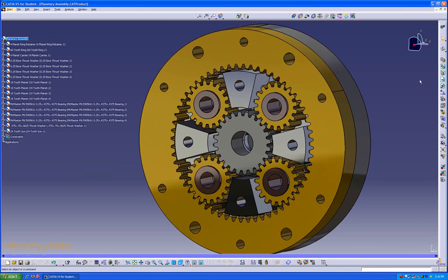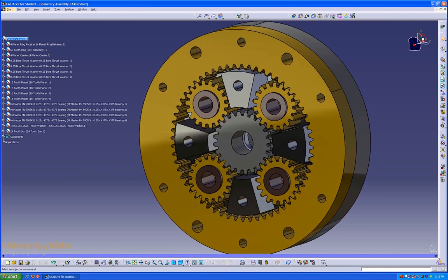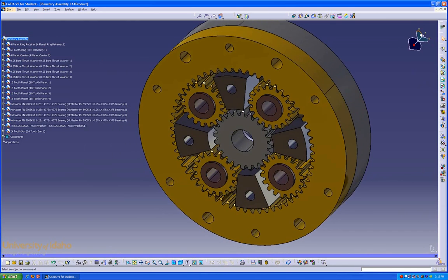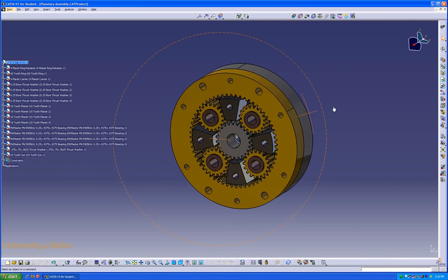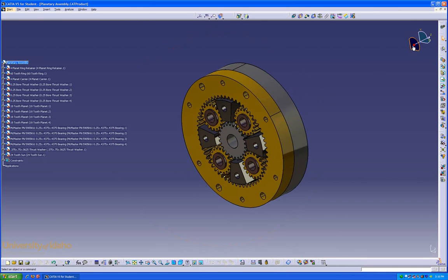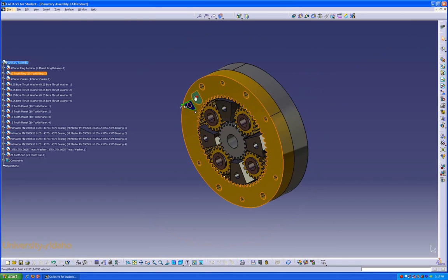The 3D compass can still be used to manipulate parts like this, but in an assembly workbench, it has a different usage in that you can click and drag on the red of the compass and it'll snap to faces, planes of your part and allow you to manipulate them.